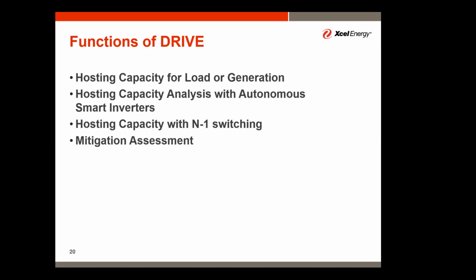To your question, Yoki, the mitigation analysis began really a little bit before Xcel's filing last year, on how to get the feeders that had zero hosting capacity up to an ability to accommodate DER. We have further refined that analysis, but the general idea there is looking at feeders that may have zero or just a limited hosting capacity.